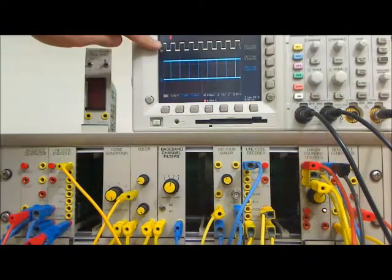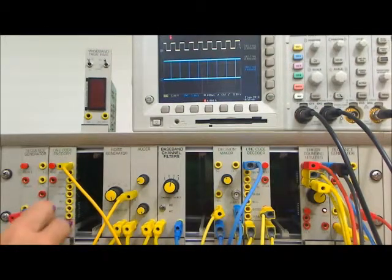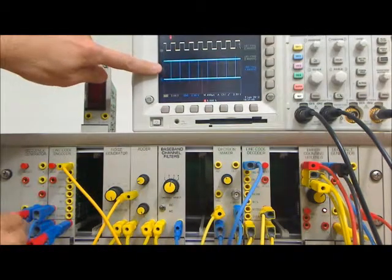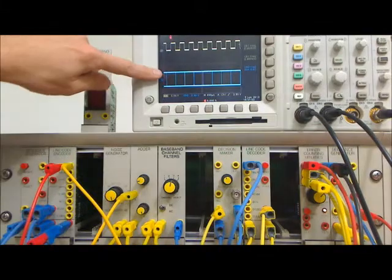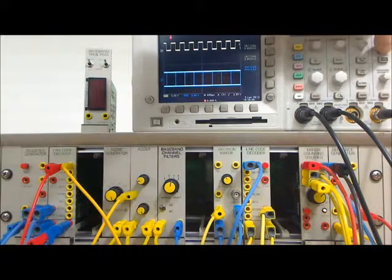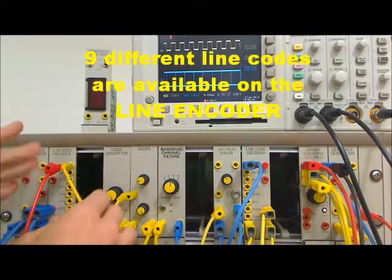On screen we can see we have the bit clock, 2 kilobits per second, and as well we are viewing the digital data output from the sequence generator. Removing the probe, we have a look at the output of the line code encoder, which if I single shot it, you can see that it is plus or minus 2 volt level shifted signal.